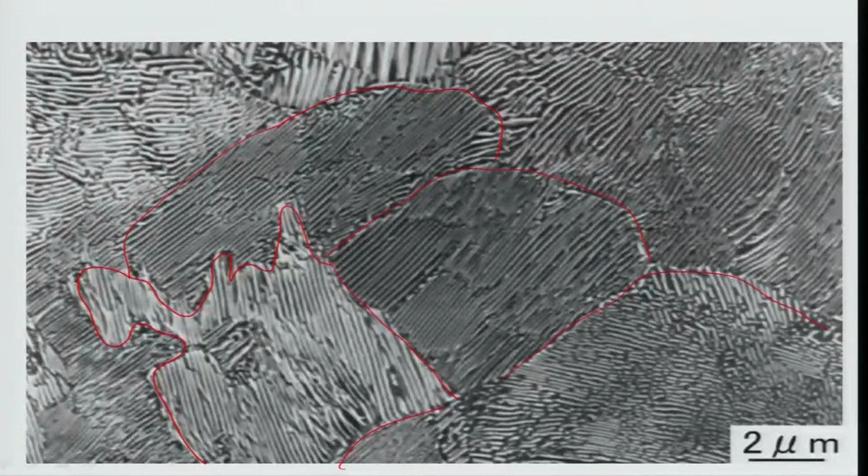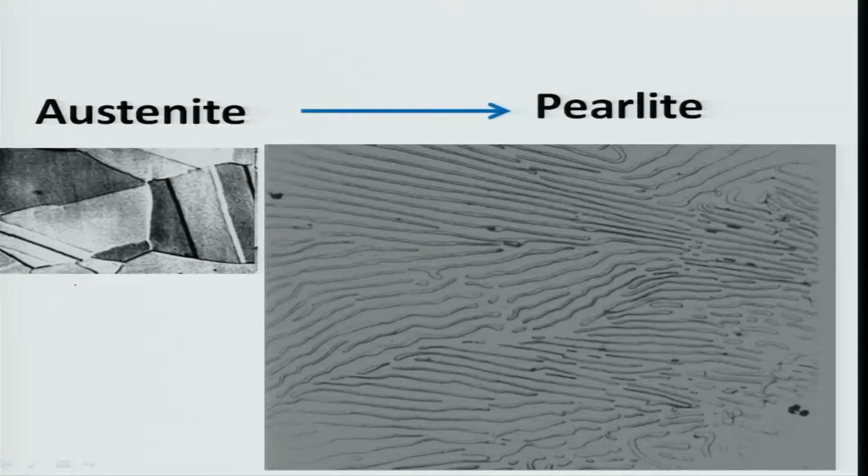carbon plain carbon steels. So, in a nutshell, this is austenite, and if you cool it down below the A1 temperature, it becomes pearlite of this type. This is a very important thing I told you. In pearlite, cementite is a very hard phase, whereas ferrite is a very soft phase. Because of this mixture of a hard phase in a soft matrix, because the predominantly large areas consist of ferrite, that is why it is called the matrix, and the cementite is a very small fraction of the microstructure. This has wonderful mechanical and physical properties because of this in situ composite which is prepared during this reaction, and which is unique in the world. No other systems can show this kind of microstructure. That is why steel is so widely used in applications.